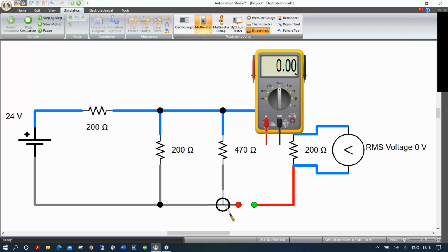And it's like a bit of reality, you know, if you have a breadboard, you have your resistors, you need to connect them together. So this is kind of a way of using it. Let's go now for current. So I'm going to actually take my probe, drop one here, and drop one here to see the current. But you see, my current is lower than what I have here. Okay? So I will need to actually use a different tool to measure that low current.